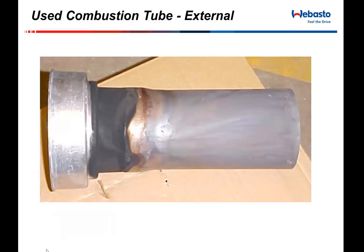When you pull this burner tube out, you can look at it and really get a good feel for what's going on with the product. You'll have about 2 inches of carbon up on the front end portion, and then the bottom portion here should be nice and clean. This is the hot area, so anything on this portion is burnt off. This is the cool area where you'll get a little bit of carbon built up.